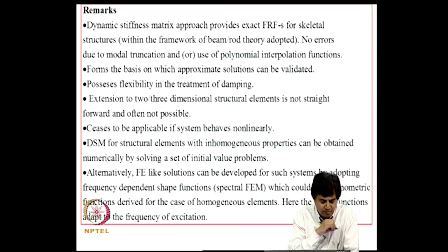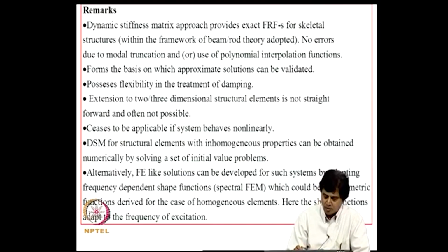Then the problem with the dynamic stiffness matrix is that extension to 2 or 3 dimensions, for example plate or shell problems, is not straightforward and often is simply not possible for various boundary conditions and geometries and so on. Also, this method ceases to be applicable if the system behaves non-linearly, because the basic fact that we are assuming is that a harmonically driven system in steady state responds at the driving frequency harmonically, and that property is valid only for linear time invariant systems. So, the moment system nonlinearity is included in the modeling, this approach becomes invalid.